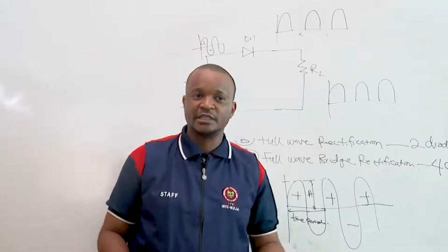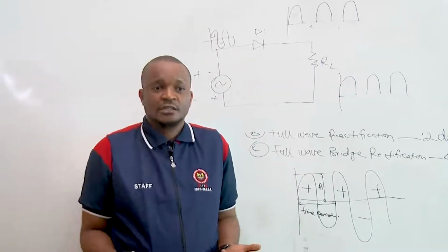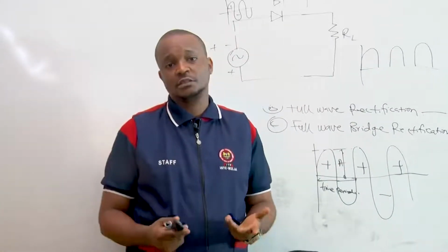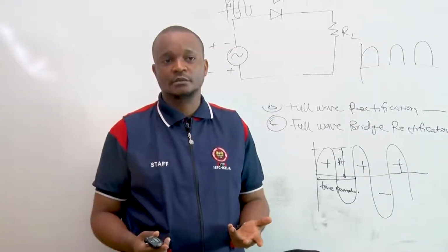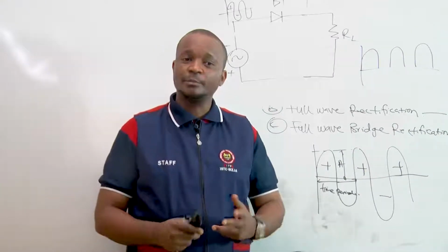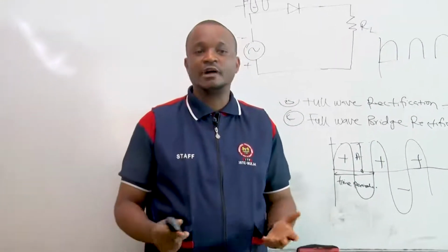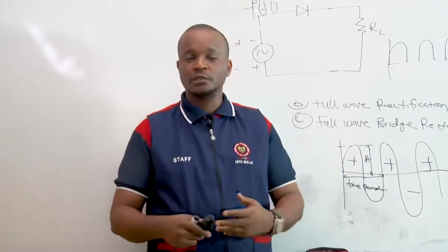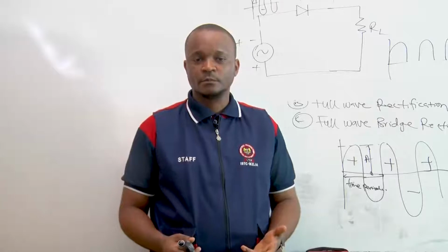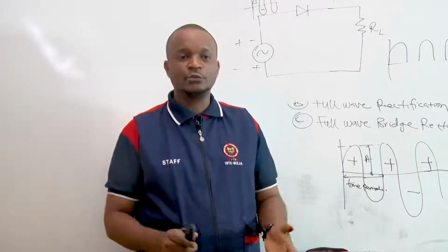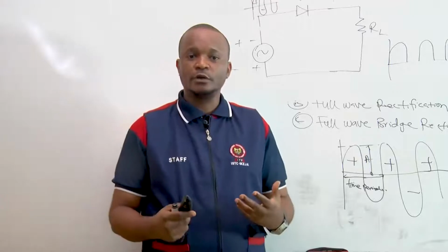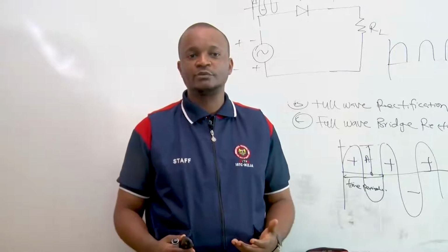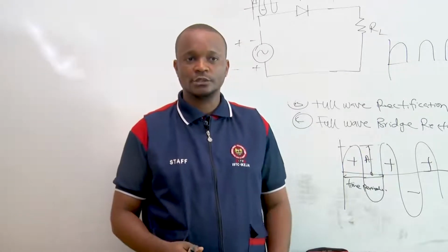However, the advantage could be in terms of cost. Since it's only one diode, in terms of cost, one can say it costs less. Again, it is useful in power supplies that need not deliver much current or that do not have to be specially well regulated. So these are the areas where you can use a half wave. If we don't require much regulation, that is an unregulated load, the half wave rectification can do the job.